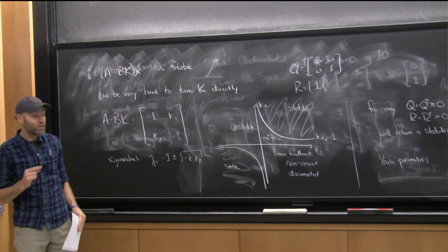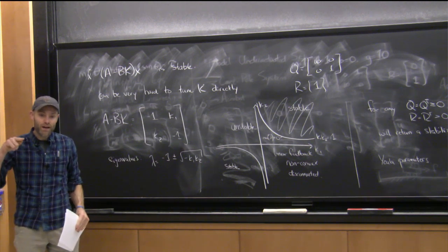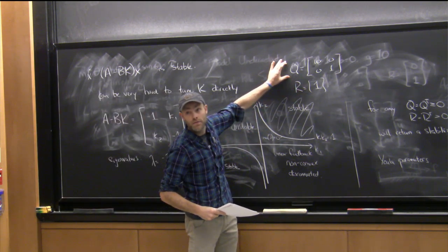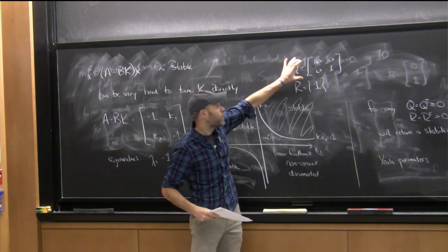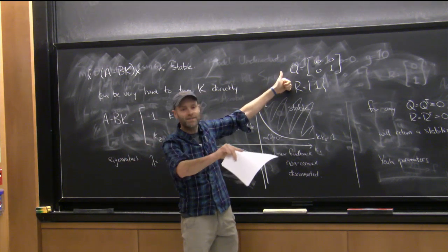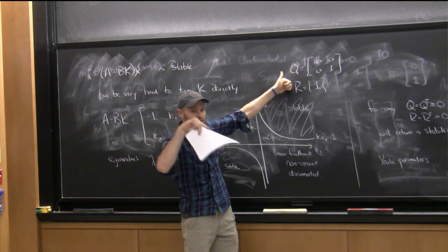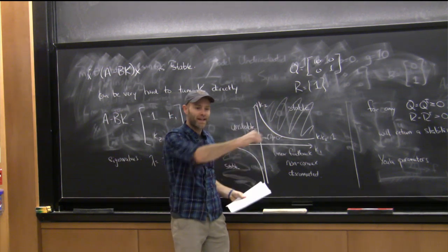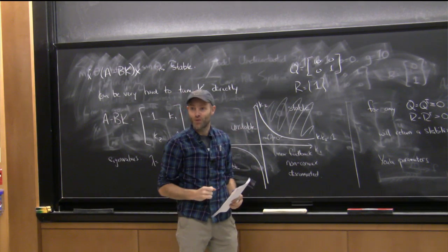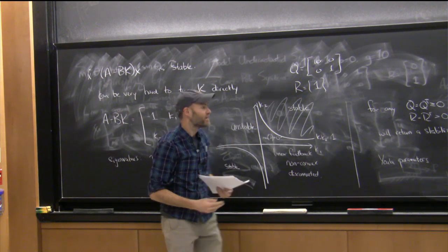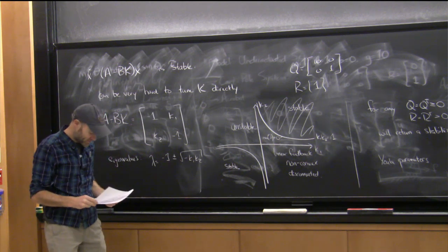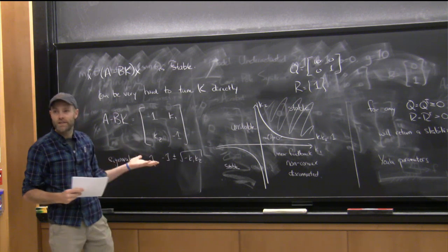But if you look for the pendulum and you do the experiment, as you crank R up to infinity, and really all that matters is the relative magnitude of R and Q, right? Because if I crank up Q at the same time, but if I hold Q fixed and I crank R up to infinity, K will asymptote, like K1 for the pendulum, the first element, asymptotes to 20, which turns out to be exactly what it would need to fight gravity. It'll never go past, it'll never let you make an unstable controller, okay? But it'll give up as much as it can. It's beautiful. It really does a lot of stuff, even though it's a linear control.